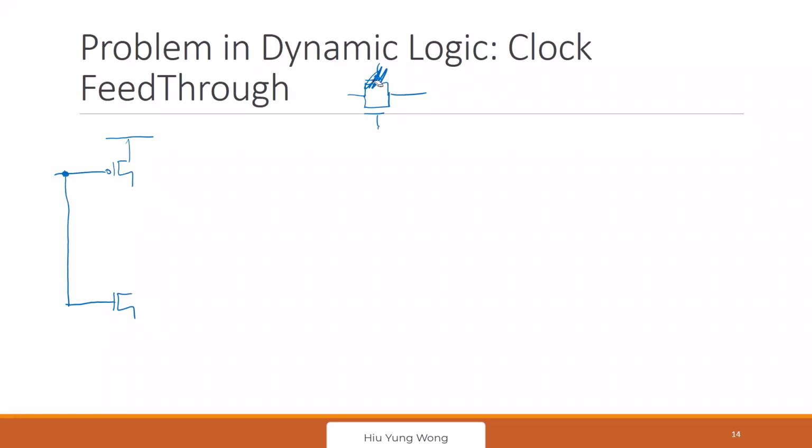I have one more thing. How do we design the clock for the dynamic logic? What are the parameters that need to be considered for the clock design? I think the most important is the delay, because you need to drive so many PMOS. So you have a constraint. First of all, what is the frequency you want to achieve? And then you need to look at all these PMOS. How are they going to slow you down? You cannot just optimize locally, because the single clock is driving so many gates.